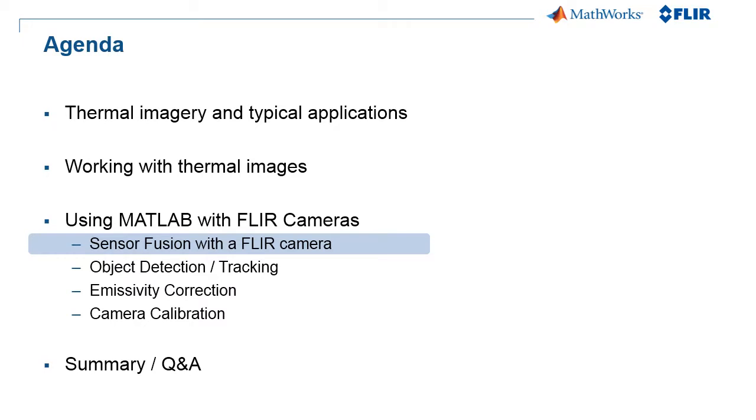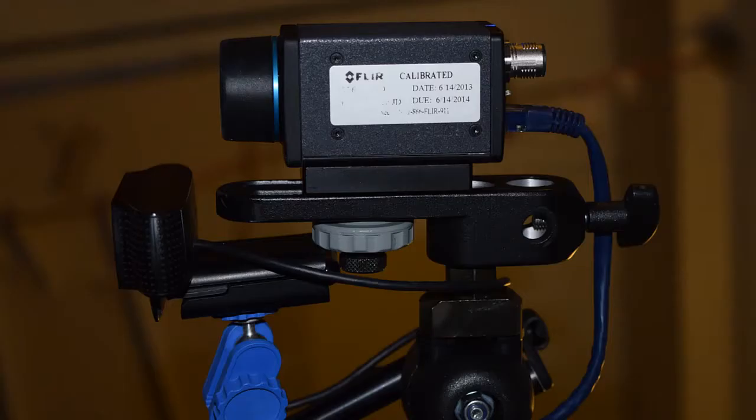So Dave, coming back to, you said some of the ways that maybe MATLAB can help to extend the capabilities of a camera. You mentioned fusing sensors. So actually, here's our first example. If you see our image here, my current setup, I actually have one of your cameras here. This is one of your test bench setups. I think it's a FLIR A35sc benchtop test kit. Great. Yeah. And you can see I'm connected through Gigabit Ethernet, GigE Vision, and I'm using a webcam below.